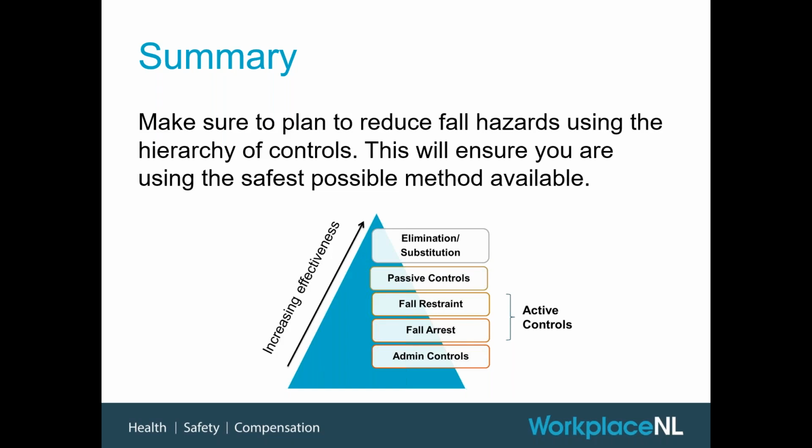Again, I mentioned the 4-foot rule that one employer I know at least used for a time. So their rule was to tie off at 4 feet. So if they had to get up and, say, change the light on a big piece of heavy equipment, they would have to get a scaffold realistically, because tying off was not going to work. The clearance was not sufficient for that system to be appropriate. But I see that a lot. I see people tying off at heights where it makes no sense to tie off, because with the length of their system and what have you, they're going to hit the ground. So again, you want to try to explore the safer options first.